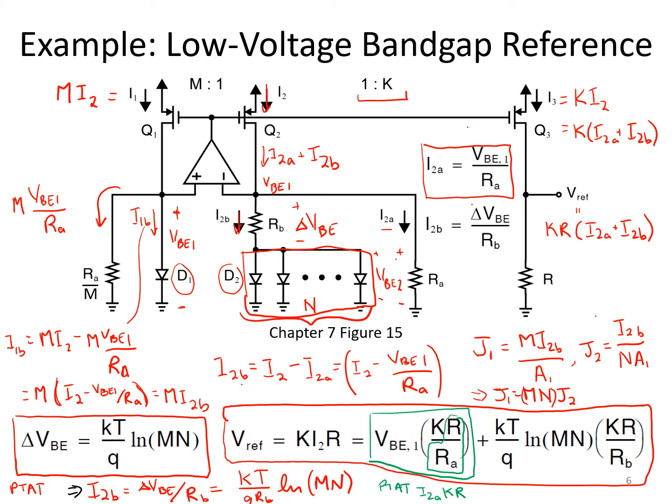That way, their temperature coefficients should all be matched and should all cancel in the final expression for VREF. And at the same time, we can ensure that these ratios are fairly well controlled, within the mismatch accuracy of the process technology.